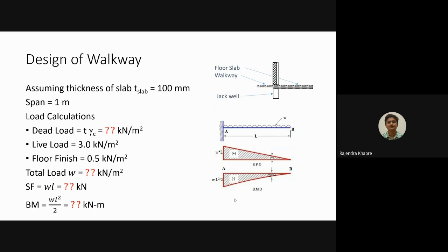Okay. And you have to keep the reinforcement in line with the main reinforcement, because the same reinforcement of the main slab will go outside. Otherwise there will be an overlap. So we can assume the span of the cantilever slab as 1 meter.